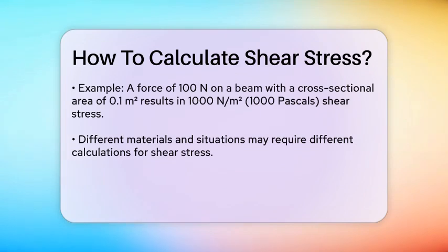In engineering, especially when dealing with beams, there's another formula known as the Jourawski formula. This is used to calculate the shear stress in beams and involves the total shear force, V, the statical moment of area, Q, the thickness of the material, t, and the moment of inertia, I, of the entire cross-sectional area.